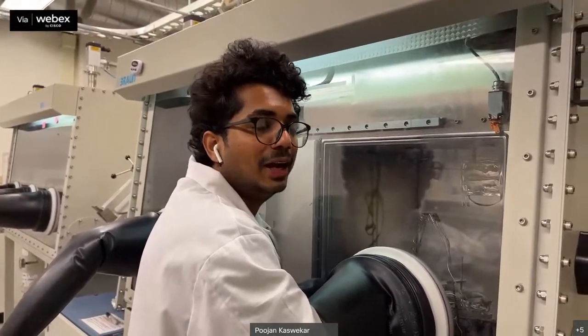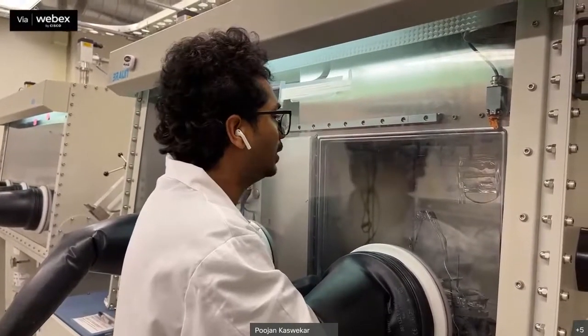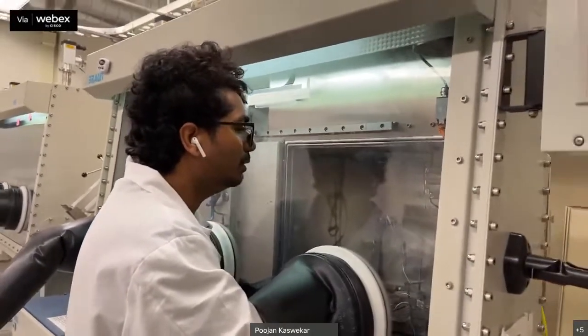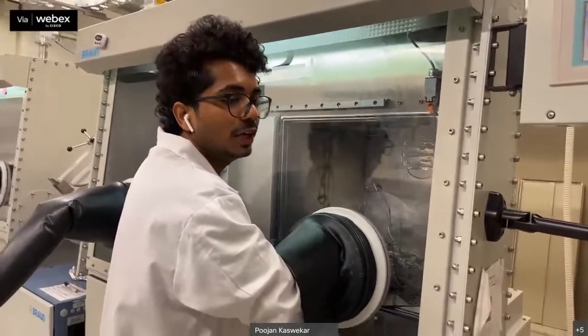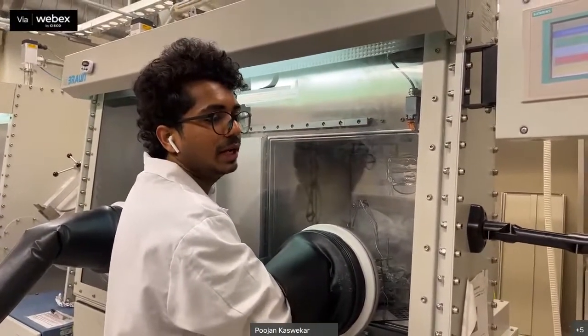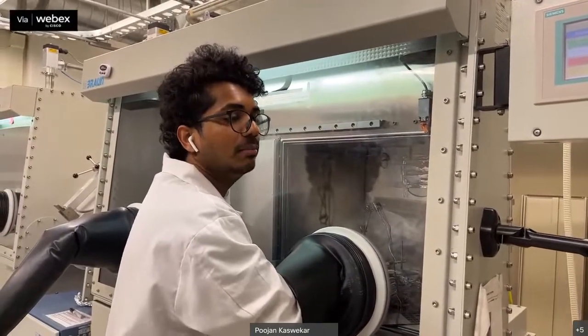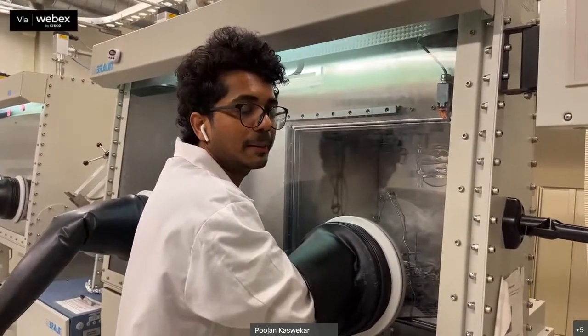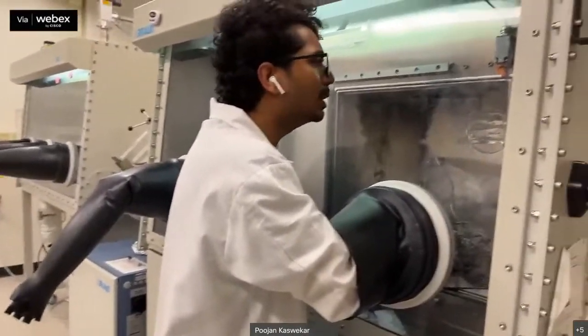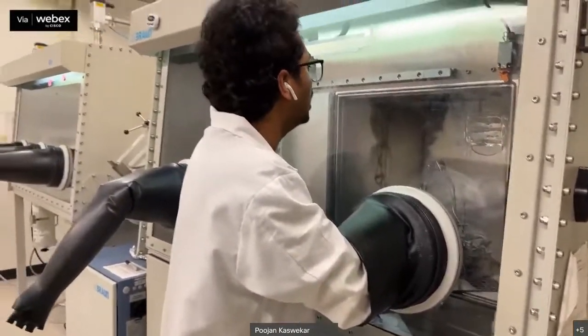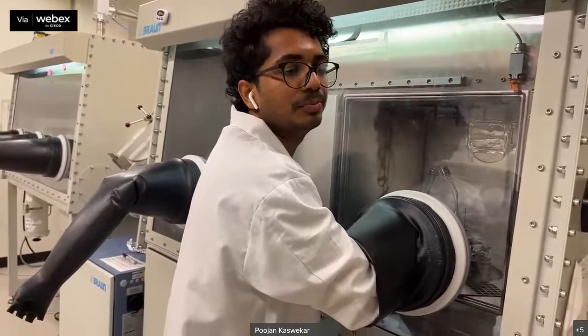Yeah. I know, like for heterojunction, for the lower area, it will impact the roughness. When you go to the ITO, it is only 40 nanometer thickness. That's why we care more about sheet resistance. But silver, it is 80 nanometer. So that's why we didn't care much about it. But yeah, that's a good thing to do. I'll measure and I'll let you know.